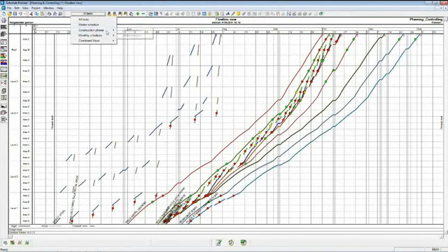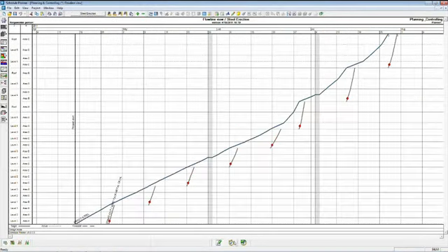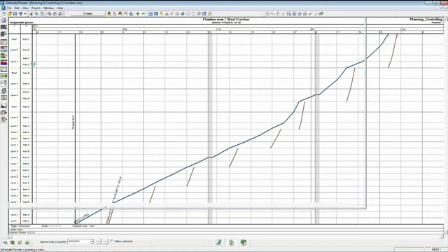Let's do structural steel. Take a look at the steel erection. We're going to move into what we call control mode of the scheduling interface here. And let's say that we're working with superintendents on the job site. Every week they walk the site with the subs. The project engineers are out there walking the site. They're recording the actual work complete so that we can input this actual work complete back into the system and use it for forecasting. And the way we do that is by using the task control chart.